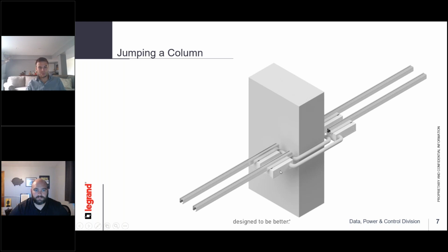On anything 600 amp and below, busway amperage wise, you could use a terminal block like you see here. So all we're doing is turning a terminal block into here and here, and then we're just using a hard pipe conduit coming all the way across, okay, and bouncing back and forth. Do you see these in data centers, Corey? I see them a lot in industrial.